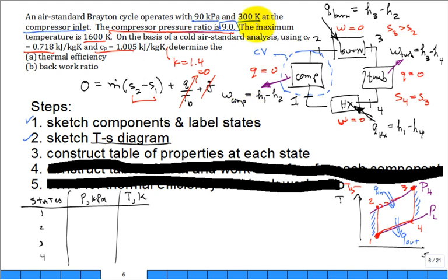Because when I come up here, let me flush that out. What is H1 minus H2? Is it C_P times T1 minus T2? Yeah, that's what it is. All right, how about up there? Is this H3 minus H2, when you make that additional assumption of constant specific heats, C_P times T3 minus T2? Yeah, that's right. And then down here, it's C_P times T3 minus T4, true? And then this would be C_P times T1 minus T4.